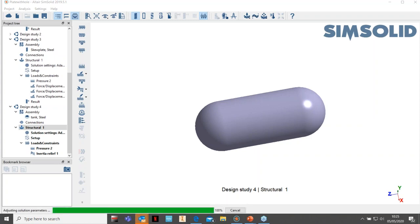So what it's doing now is going through all the convergence process. This is automatic in SimSolid, so it goes through automatic convergence. And when you are comparing results for stress, it goes through 5 iterations. So not just running one analysis, it's going through 5.